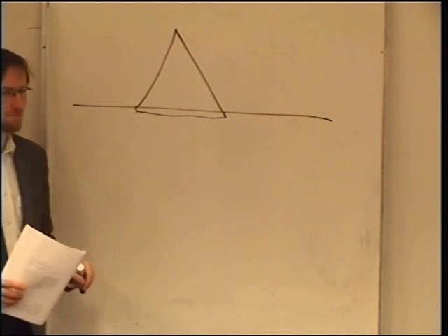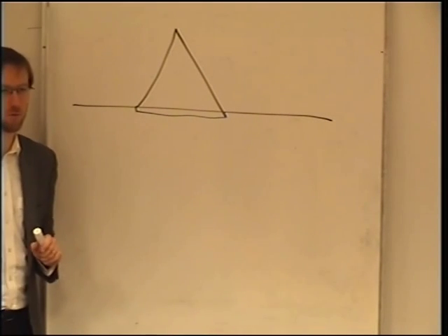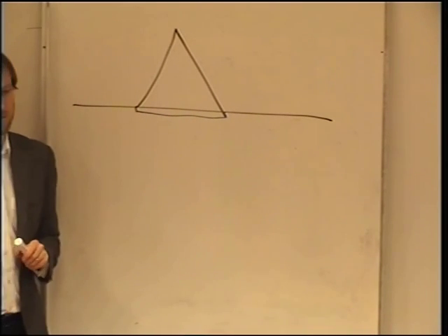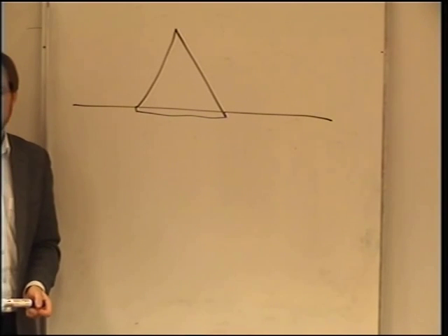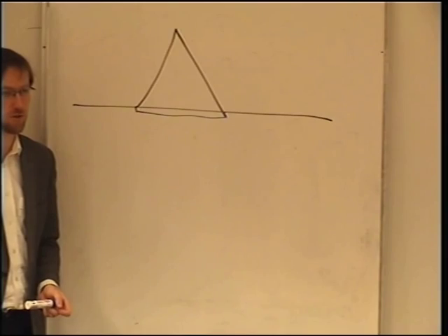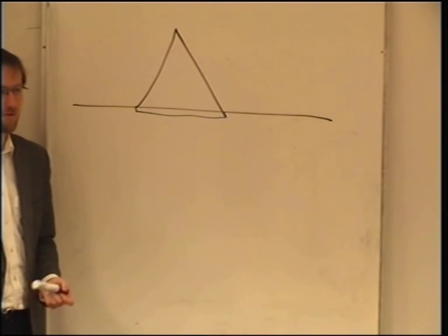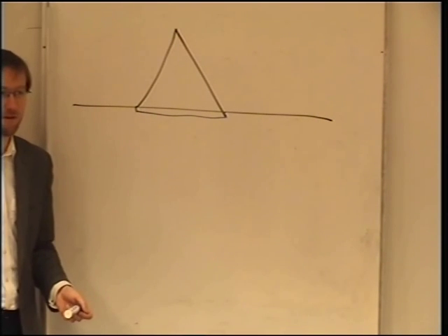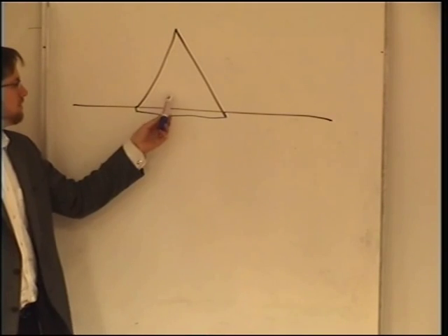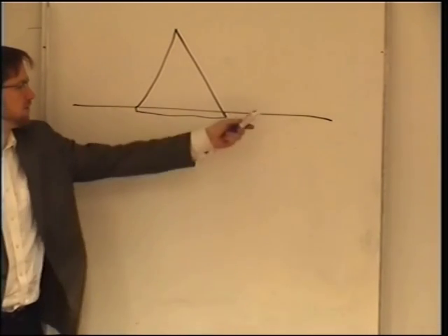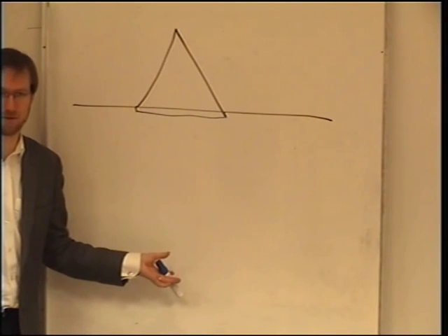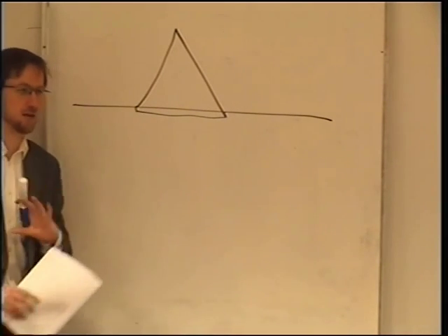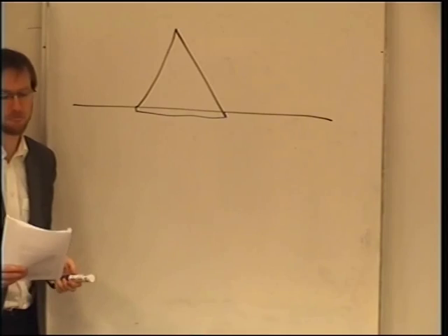Now, these are the functions of compact support that are really interesting in finite element land. The main reason they're interesting there is because they get us a lot of computational efficiency, because it means that the matrix systems that we end up with are very sparse. If this function is here and some other function is over there and their supports don't cross, then we don't get any entries in the matrix. So that's the normal finite element reason why compact support is interesting.